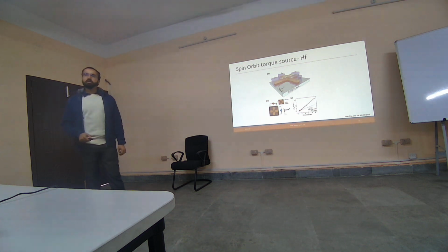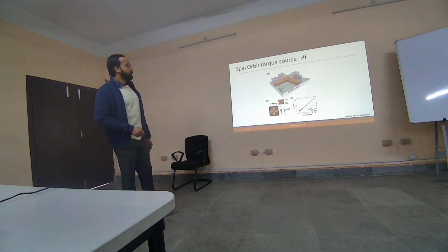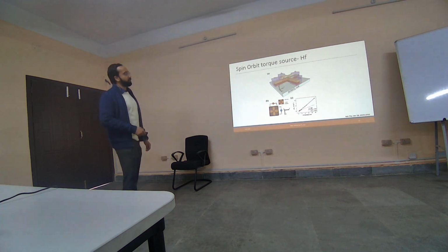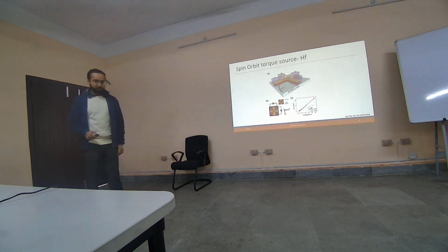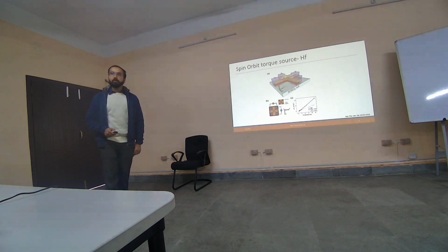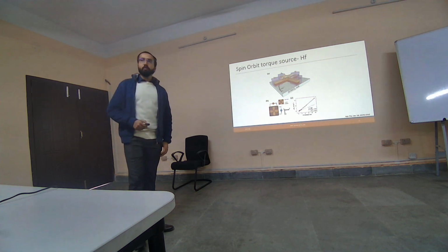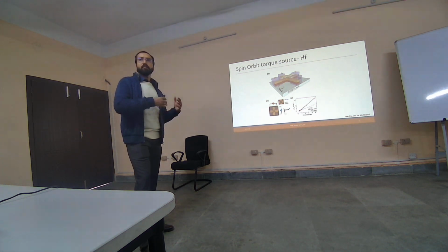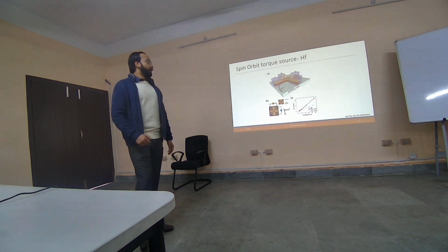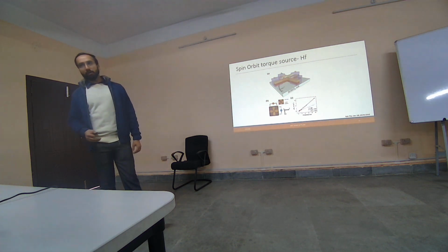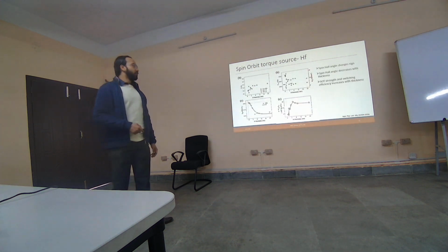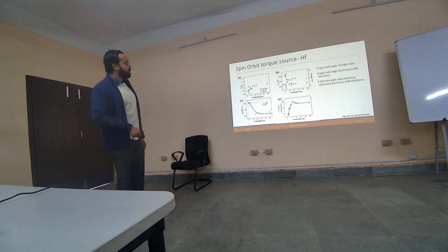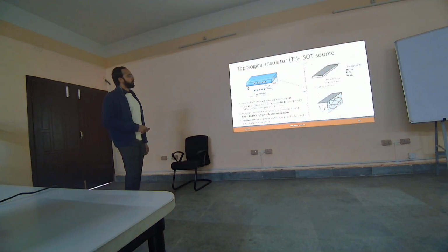10 micron, the device size. Okay, so this is one of the work here. So here what we did was we used hafnium. It's a material which is known for its high spin orbit coupling, and we were able to generate... I told you spin orbit coupling leads to spin Hall effect and therefore leads to spin orbit torque. And because hafnium had very high spin orbit coupling, we were able to generate very high spin orbit torque in this work. Okay, so this I'll probably skip through because this doesn't matter so much.